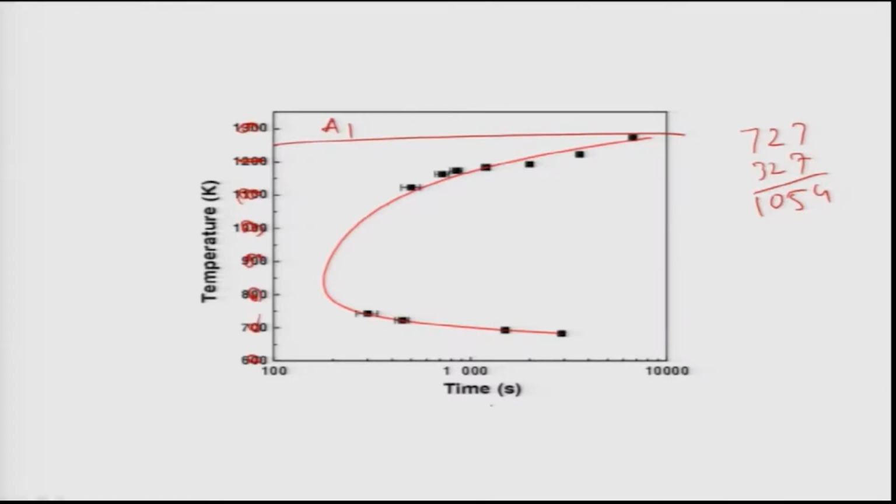And this is a time scale in logarithm scale. As you see, this is the 727 temperature for the steels. Above 727 it is always gamma. Only at lower temperature does it transform to many products. For the pearlite, when it is close to 720 Celsius, undercooling is low, so nucleation and growth is very slow, correct.